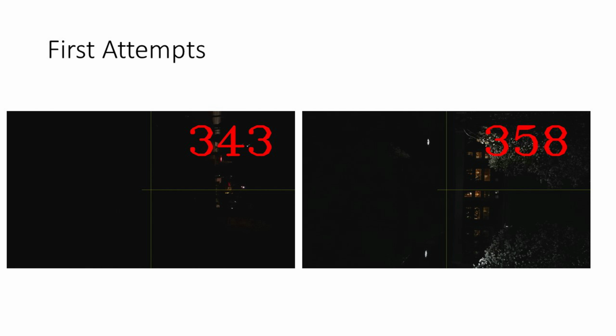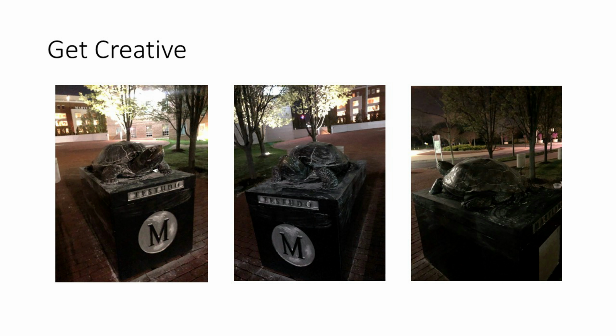And after repeated attempts at filtering and using saturation code, we still get no returns whatsoever. So then we have to think back to the LiDAR equation, and one of the components of the LiDAR equation is the scattering coefficient. So we're going to increase the scattering coefficient here, and the way we're going to do this for the statue itself is to add flour all over Testudo. And we do this by covering him in every orifice we can get to.